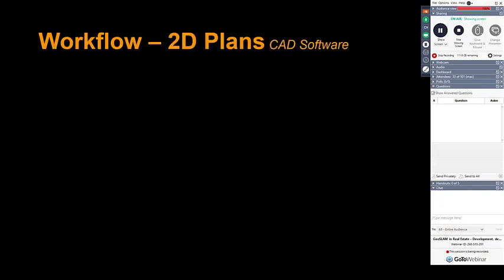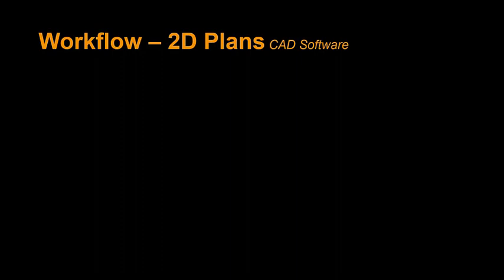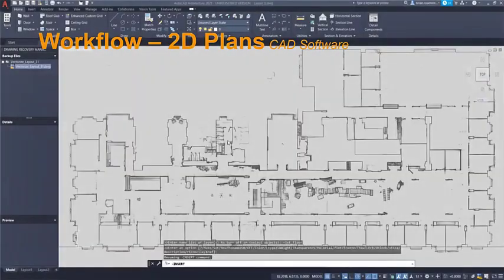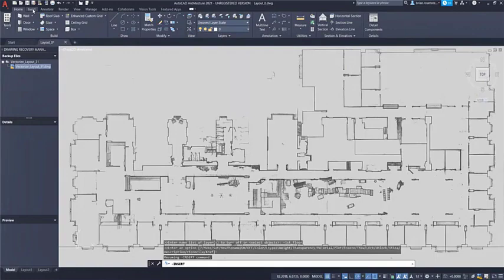So next we'll talk about what the workflow looks like into creating 2D plans in a CAD software. Again, this is going to be in AutoCAD, but we're going to take those elements, the ortho images, the vectorization, and the point cloud that we just exported out of Draw, and bring them into AutoCAD, which is really quite simple. So we're going to start with our ortho image here. So we just bring in the ortho image.